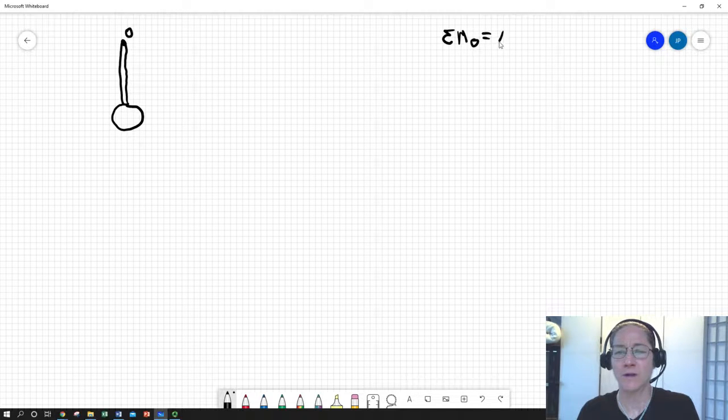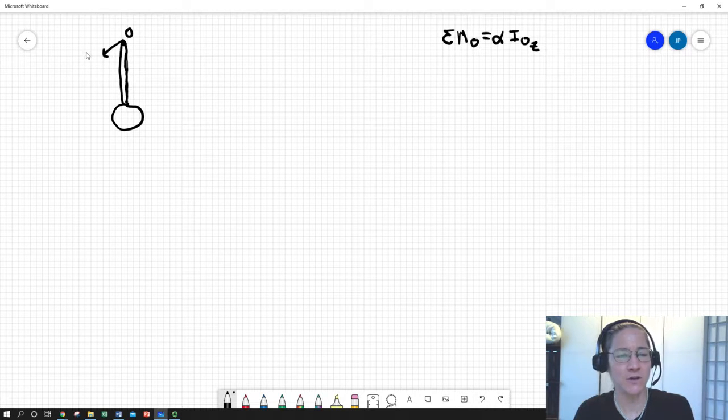would equal alpha, the angular acceleration of the full rigid body, times I_O. And this is basically I_Oz. So this is looking at the moment of inertia of this lollipop kind of shaped body, which includes a rod, and it's really a straight line, about an axis that's kind of pointing, I'm drawing a little isometric here, about a z-axis that's coming out of the plane of the screen.